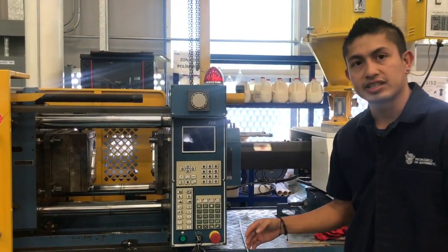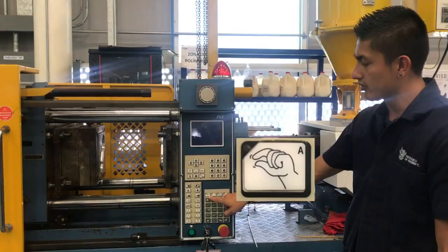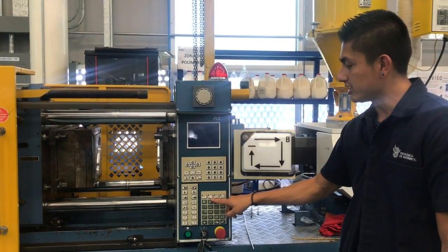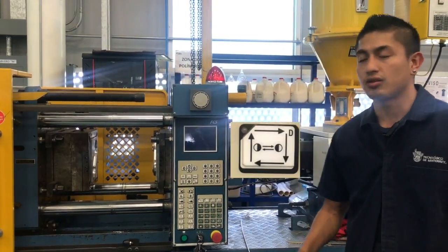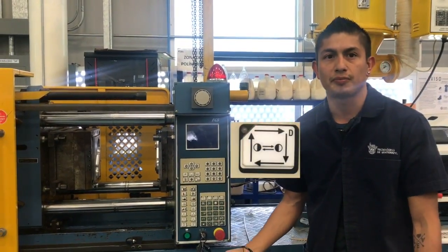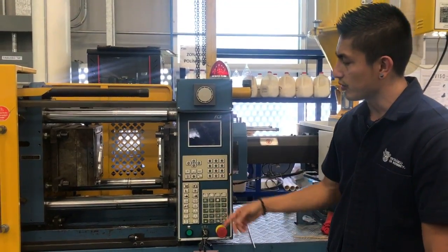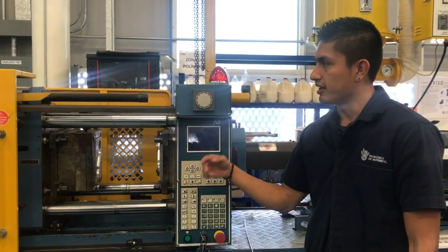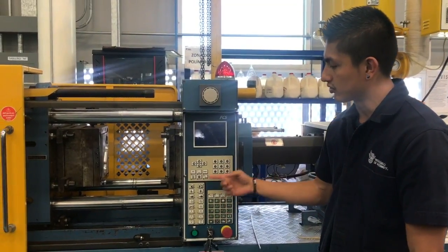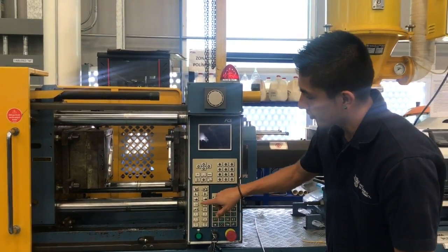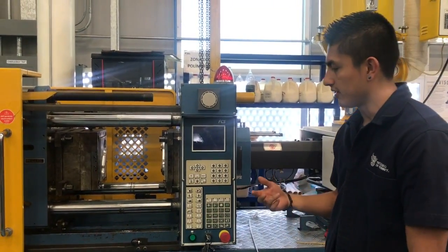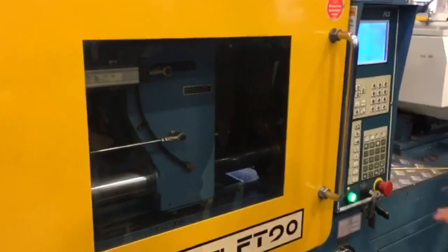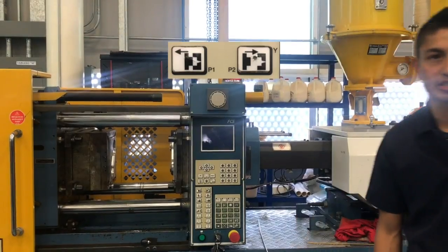We have 4 stages of control. The first one is manual, the next one is automatic, the next one is automatic with time, and the final one is the automatic with the sensor of pieces. And in this part we can move the different parts of the machine, like the extruder. For example, with this button we can inject more material if it is needed, and these other parts move the molds and the knee, for example.